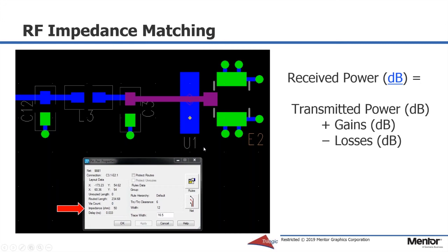This is a very simple illustration we have today, though, with just a uniform ground plane underneath of a simple 2-layer board. Just one tip for those of you who are experienced PADS users is you do have to select both the top and bottom layers as split mix planes for this pin pair property to display.